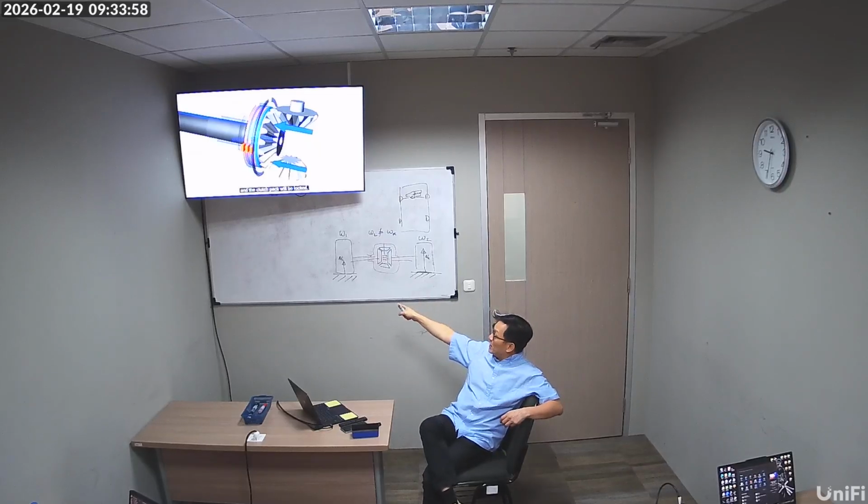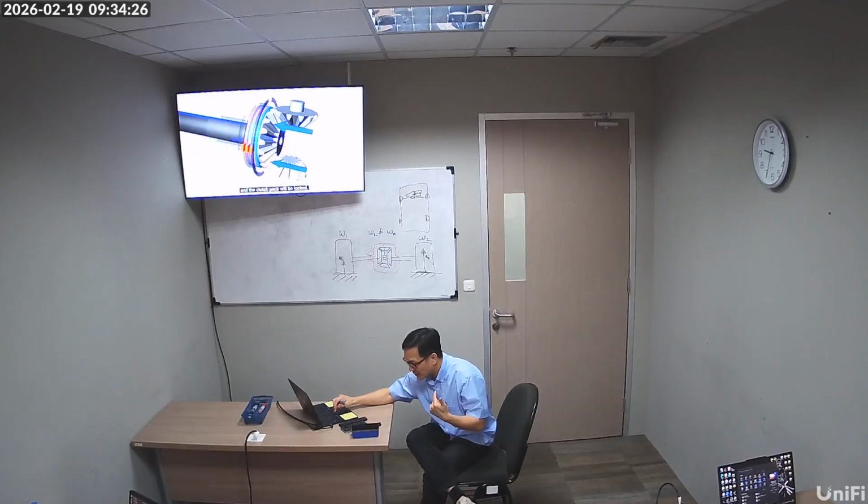So consider a situation where it is extreme, where one wheel actually hangs in the air, and then you press on the gas pedal, it's going to spin very fast, right? While the other stays still in the open differential. Now, when you have the clutch pack, when this spins very fast, it's going to attach itself to the clutch pack and transfer it to the other one. So this speed is actually going the way we want it, right?